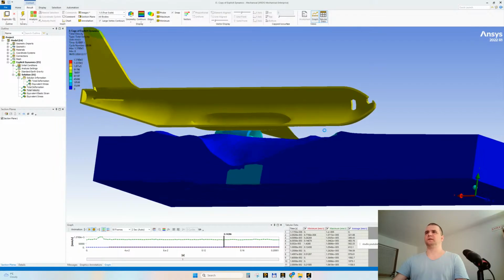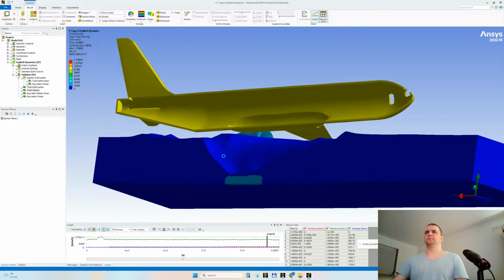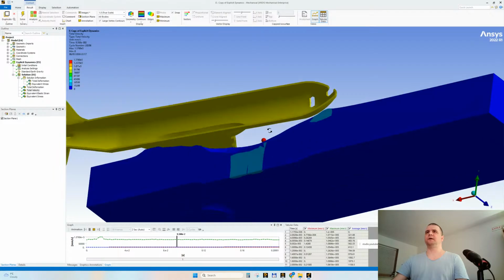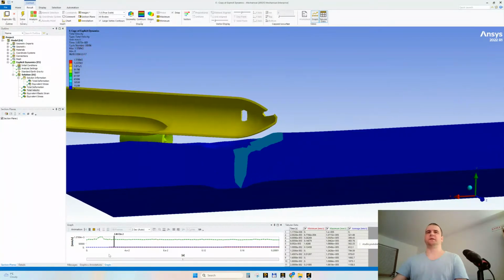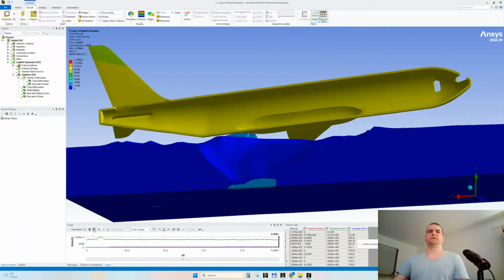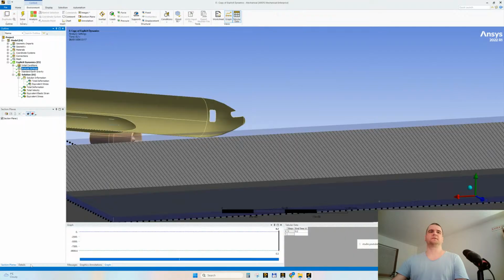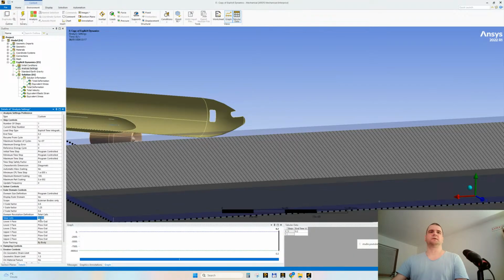In order to decrease the gap, I told you we need to refine the Eulerian mesh by increasing this number of cells, yes? These ones. I have worked maximum, I think, so there is a common sense limit, 1 million cells. I have exceeded it.